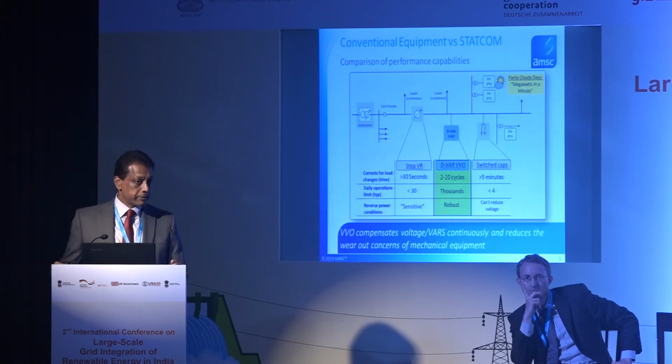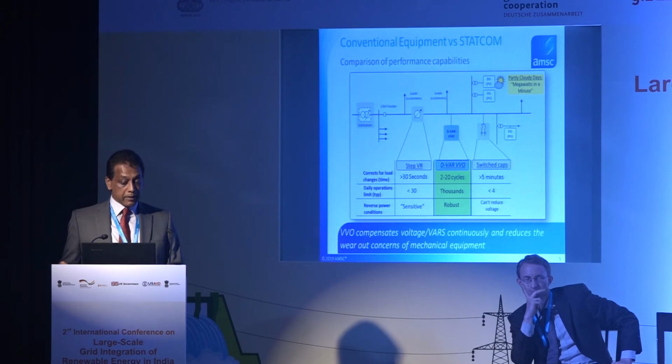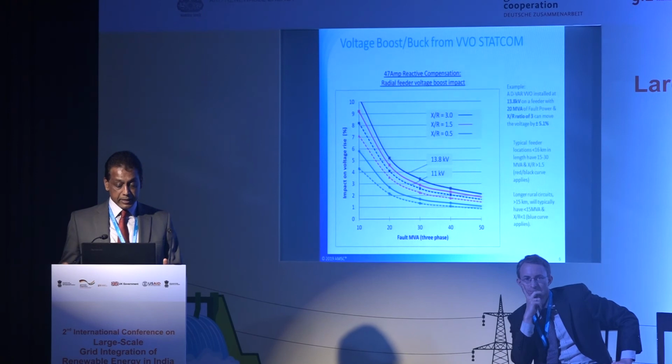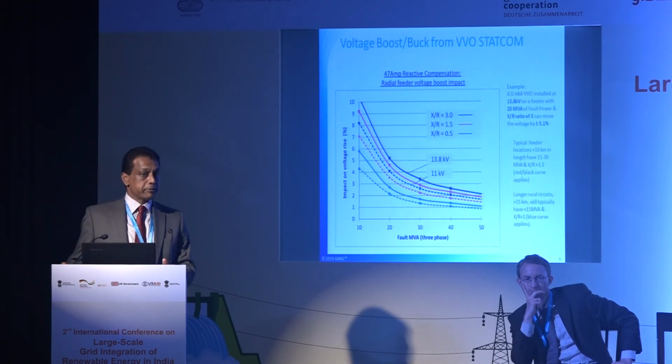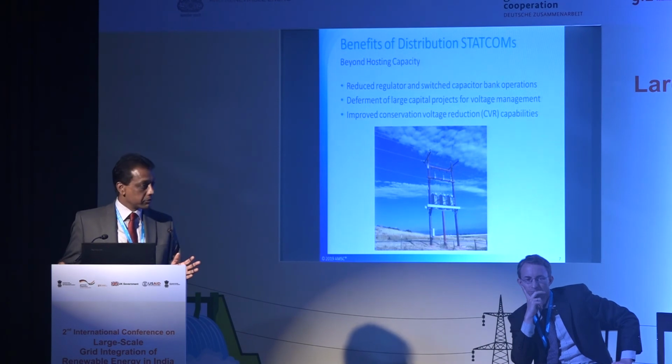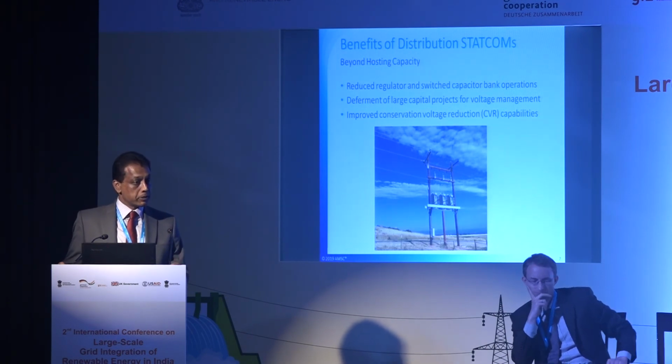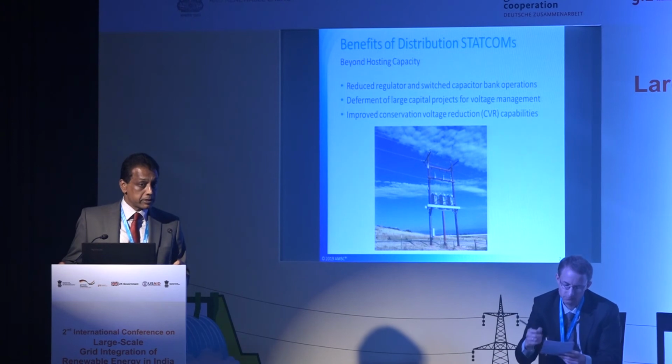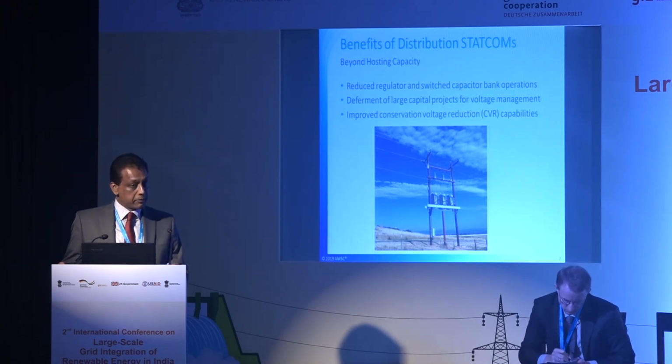Obviously, it has a lot of benefit. It can eliminate the use of cap banks and voltage regulators. It doesn't have reverse power flow sensitivity and things like that. And of course, the effectiveness of that control depends on the short circuit capacity and the X/R ratio, as I said. So I'm going to move on a little bit to give you an example of what this is. We've already deployed quite a few systems. We introduced this about 2 years ago, and quite a few systems have been deployed in the US and the UK now as well.